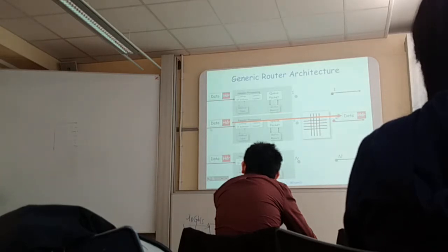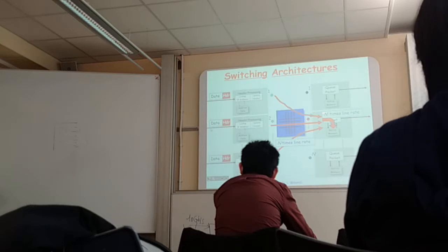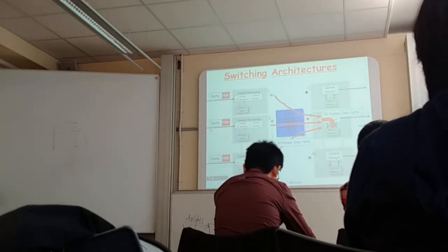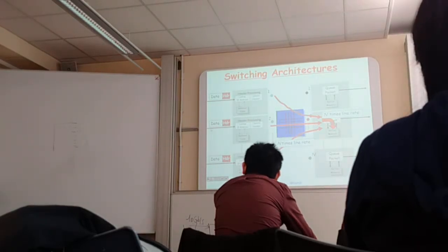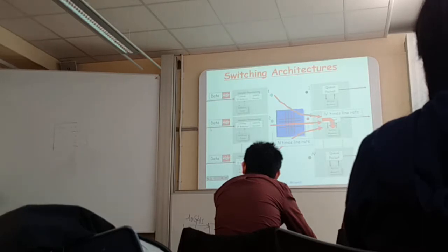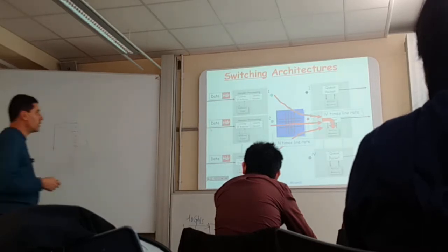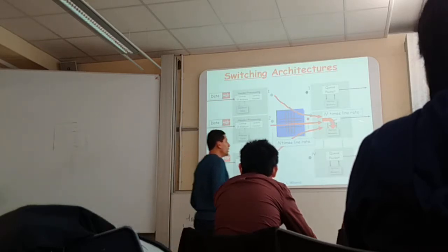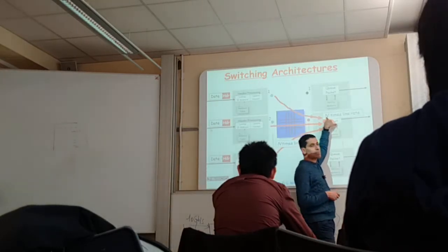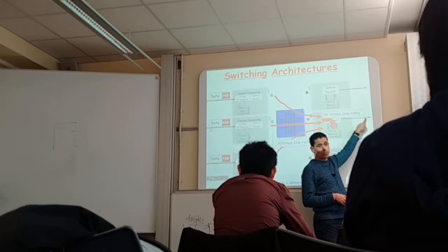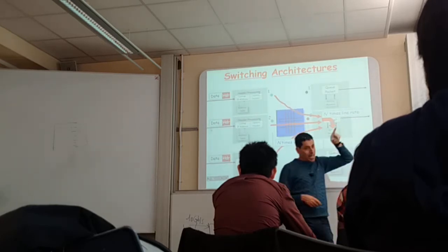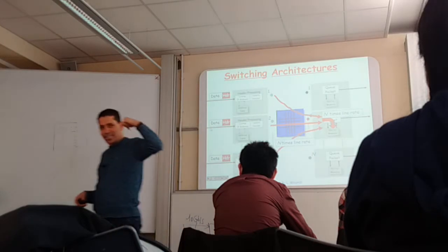This is to be compared to this architecture, this one, which is n times line rate. So the bandwidth of this memory is not only a function of the line rate, it is also a function of the number of inputs. This one is not 2n times. Why is it not 2n? Because you need to read it out. You will need to read out 1. The correct one should be n plus 1, not 2n, because you write n, but you read 1 out. One packet goes out. So it's n plus 1, you're right. But I'm leaving that plus 1 for later, I'll tell you why.